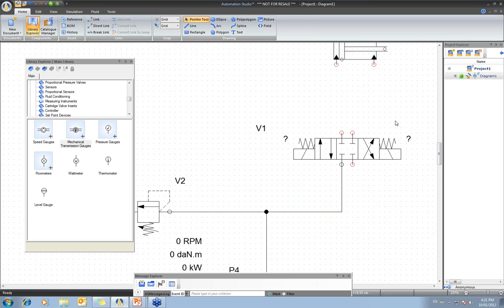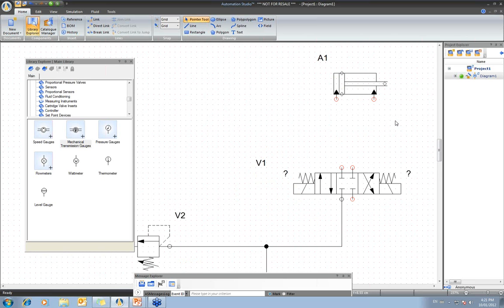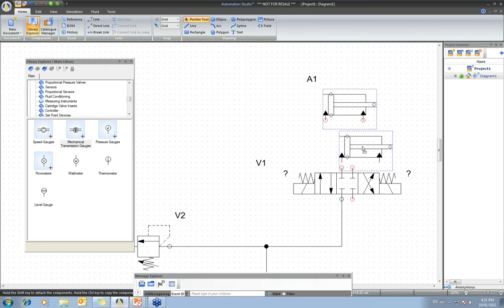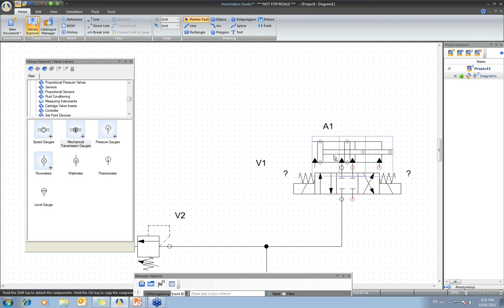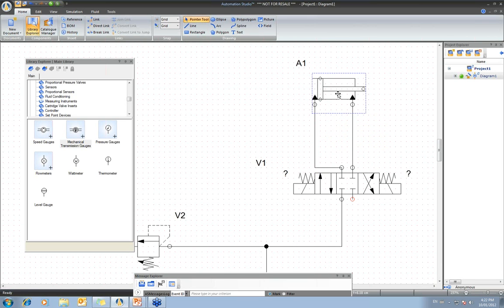Okay, and one quick way, since I said at the beginning that when you overlap the connection port, you will be attaching and connecting your line already by simply overlapping the connection port. So for attaching a cylinder like this one, it can be done easily if you simply roll over the component, move it onto the other connection port, and then move this up. As you can see, in a second, it was connected.